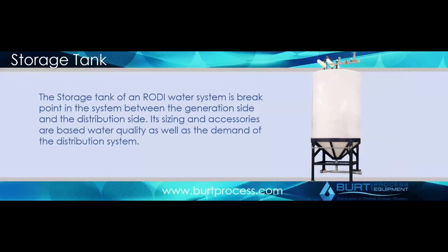In between the generation and the polishing side of your system, you have your storage tank. This is one of the things we talked about earlier: for an RO system, you're going to have to know how much water you need to make and how much water you're going to use in your loop, which we're going to talk about here in a second. Your RO or your pretreatment in general generally feeds the storage tank, and this also becomes the point where you will control the pressure of your loop.